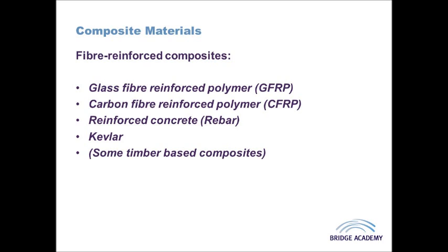This can also be noticed in things like reinforced concrete. The concrete is effectively the matrix. Now, concrete obviously is a particle-based composite in itself, but if we insert a fibre into that, in the case of this, a steel rod, I know it's hard to think of a steel rod being a fibre, but it effectively is. It's just a very large fibre or strand of steel, effectively. This provides a great deal of tensional strength to add to the existing compressional strength of the concrete.